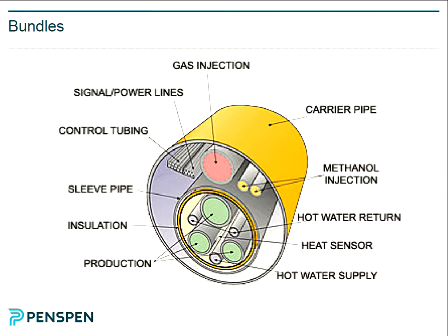They use circulated hot water to maintain the temperature of their product. Trying to think of the name of it. Britannia, I think, is the name of the field that uses this technique. It has a number of bundles, and it circulates hot water to maintain the product. The reason you're maintaining the product temperature is to avoid hydrates and wax.